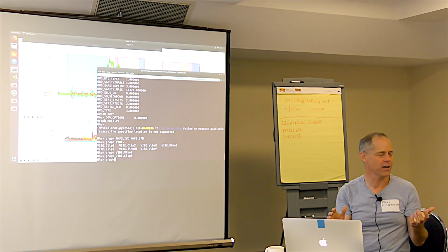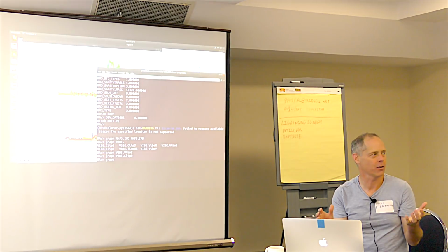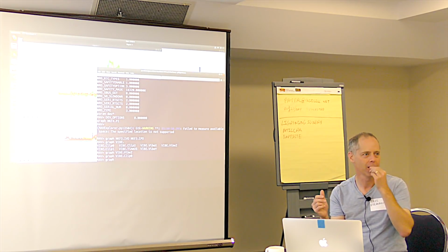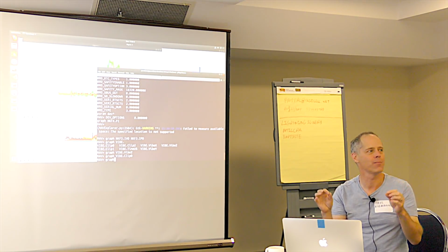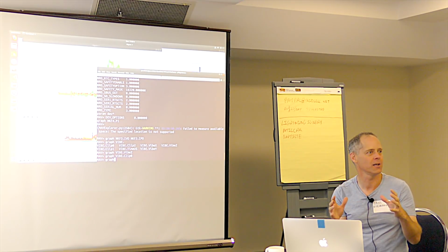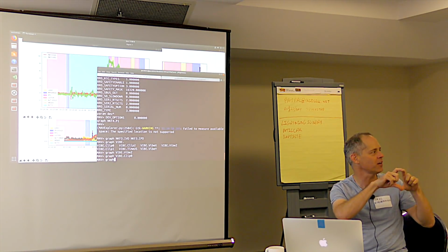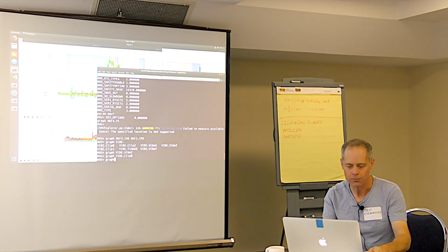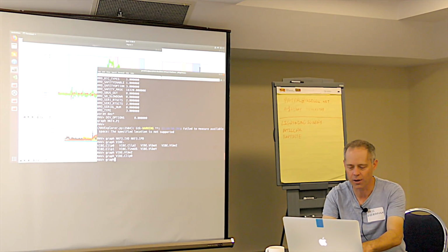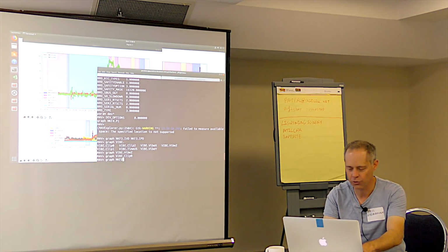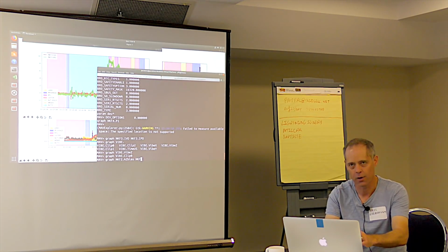So what do you do then? You've got something. It's appeared on one EKF. It doesn't appear on the other. So let's have a look at the vertical biases, because the EKF tries to estimate the offset in the accelerometers. It's in strange units, but graph NKF2.AZ bias, and I'll do the second instance of the EKF, NKF7.AZ bias.